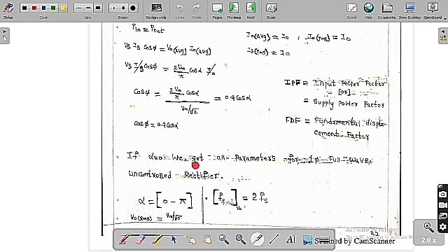If alpha is equal to 0, we get all parameters for the single phase full wave uncontrolled rectifier. If you substitute alpha is equal to 0, this whole thing is going to converge in terms of diodes, that is, the single phase full wave uncontrolled bridge rectifier. So this is going to convert into a bridge rectifier, where all the devices are diodes. So if alpha is equal to 0, we get all parameters for the single phase full wave bridge uncontrolled rectifier. Then, as I already told you, alpha is going to change from 0 to pi.